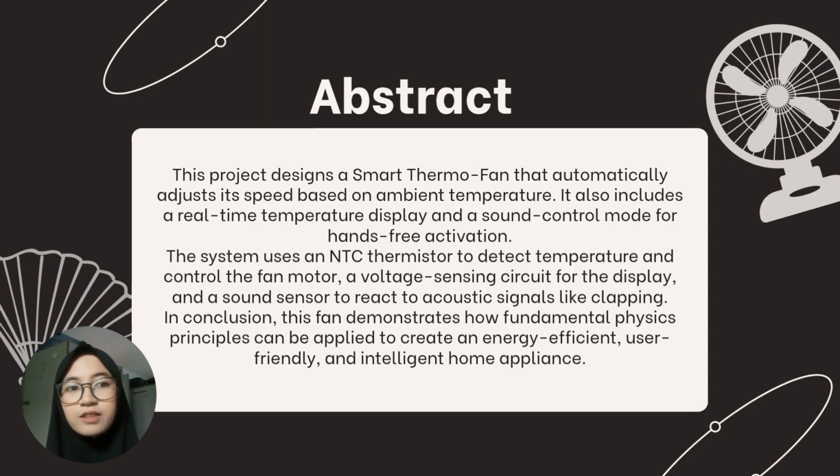This project designed a smart thermal fan that automatically adjusts its speed based on ambient temperature. It also includes a real-time temperature display and a sound control mode for hands-free activation. The system uses an NTC thermistor to detect temperature and control the fan motor, a voltage sensing circuit for the display, and a sound sensor to react to acoustic signals like clapping.